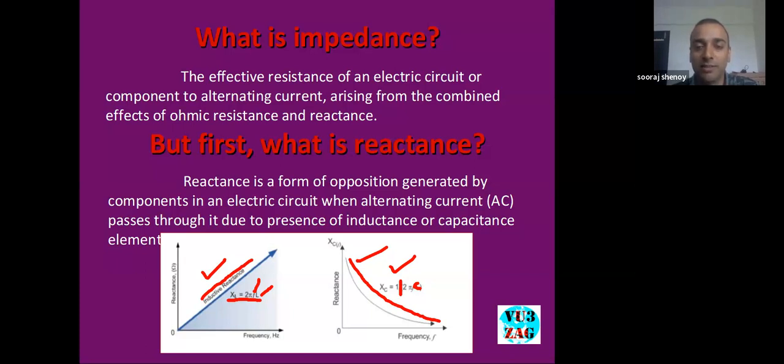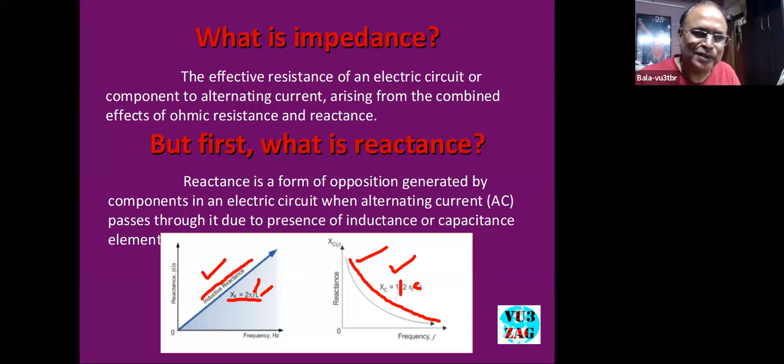If you compare this with a nano VNA in the context of analyzing an antenna, it is not comparable, because with a nano VNA we can get an entire idea of the other S parameter details and all. But this is just a simple coupler that will give you an indication of whether the VSWR exists or not. So you cannot compare that. Nano VNA is pro level, in layman terms. Hope you got my point. Yeah, I agree, there is no comparison between those.